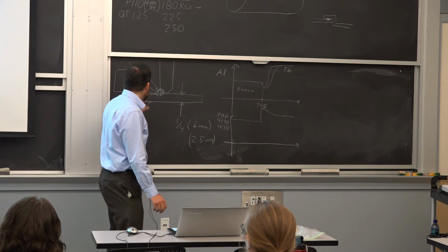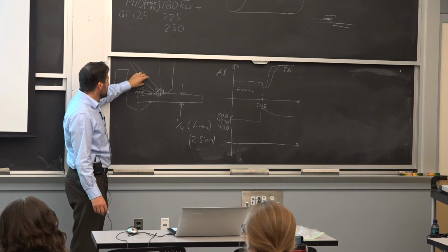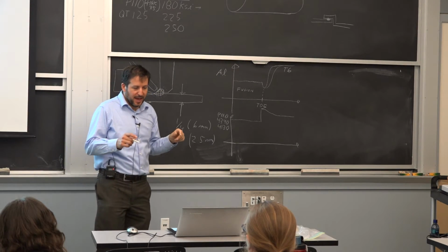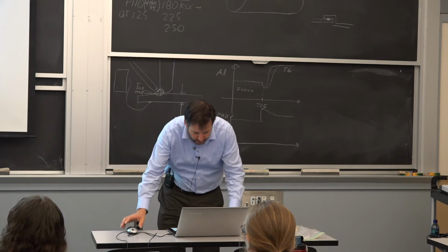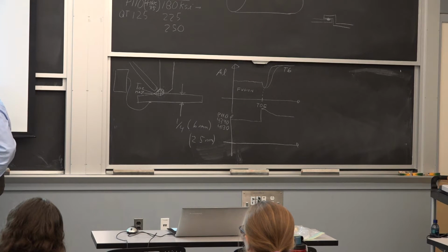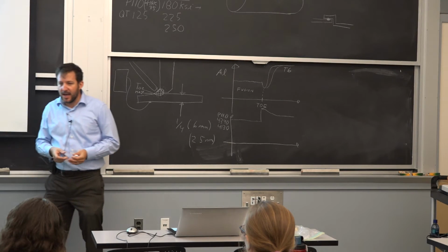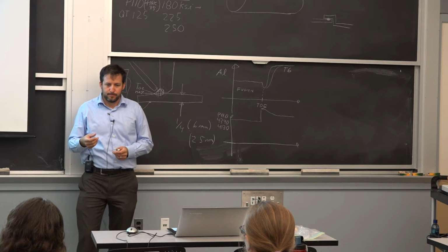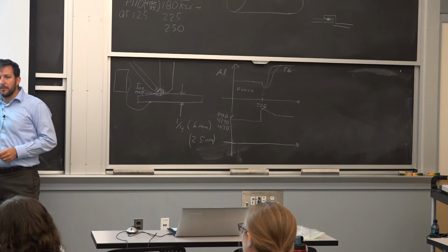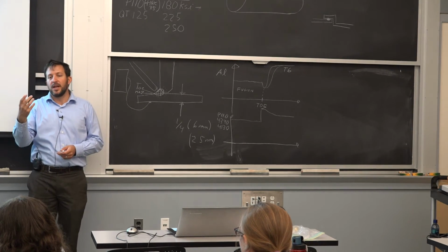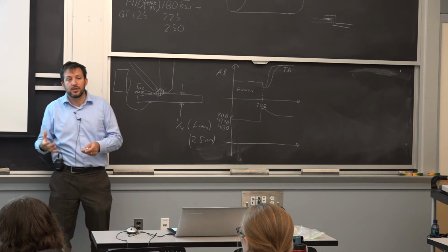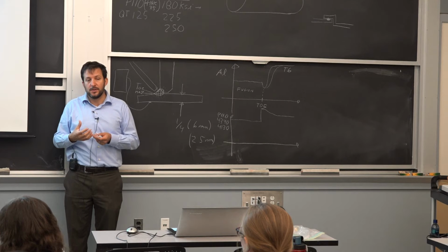In the case of the shielded metal arc, there's a consumable here that creates what we call a slag. So it's an ionic liquid that goes on top here of the fusion metal, and it has a high affinity for oxygen. So if there is any oxygen in the weld metal, it will diffuse to that zone. So the activity of oxygen in the slag is much lower. So it brings all the impurities in.